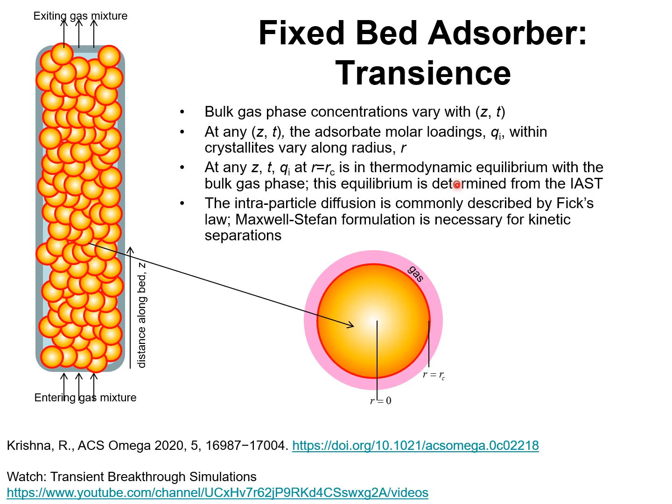This equilibrium is usually determined by use of the ideal adsorbed solution theory. The intraparticle diffusion is commonly described by Fick's law or the Maxwell-Stefan formulation, which is really necessary for use in kinetic separations.